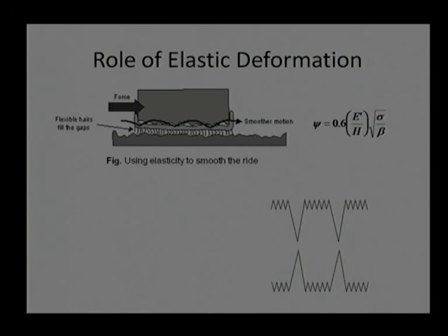How can we do that? First, if the surface roughness value is high, as in the typical figure shown here, you can see the peaks and valleys. Certain peaks are coming out, which is harmful for the machine component. If this surface roughness is higher, naturally the plasticity index will be high, and because of the high plasticity index, there will be some deformation on the surface that will lead to a reduction in service life. Then another one is Young's modulus.